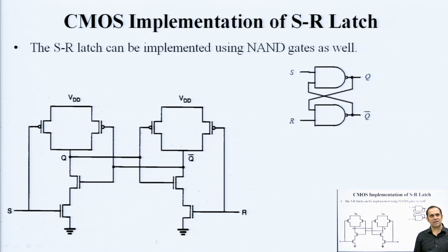Active high basically means that they will be true when the signal supplying them, or the wire supplying them, is at high voltage. So, a NOR gate SR latch is an active high component, and a NAND gate SR latch is an active low component.